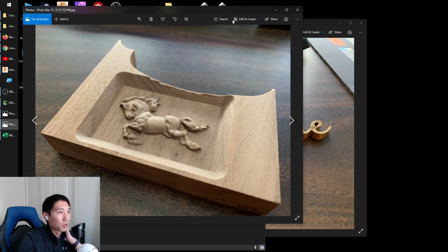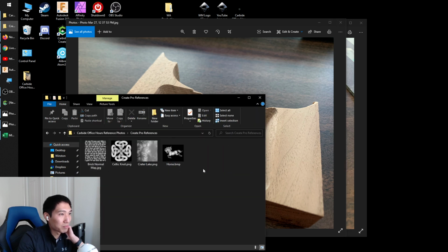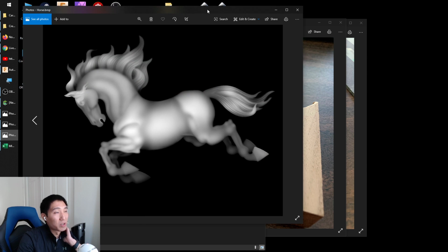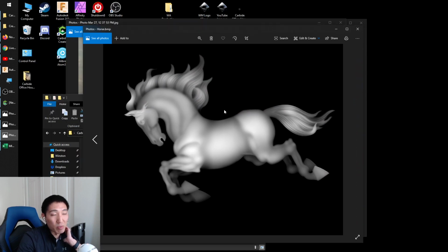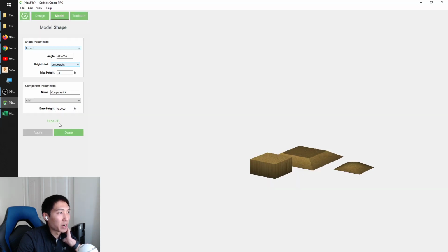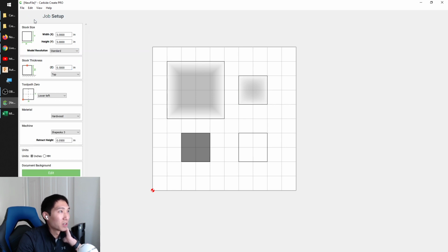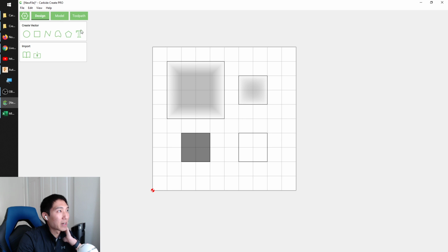You can make a carving that looks like this. This is a rectangle built on top of another rectangle, but with a subtracted chamfered edge. And then in the resulting pocket, I added in a grayscale height map that looks like this. So white represents higher areas, dark represents lower areas. You add these on top of the features you're creating and superimpose them, and then you can create different things to carve. So I can run you through how I designed that.